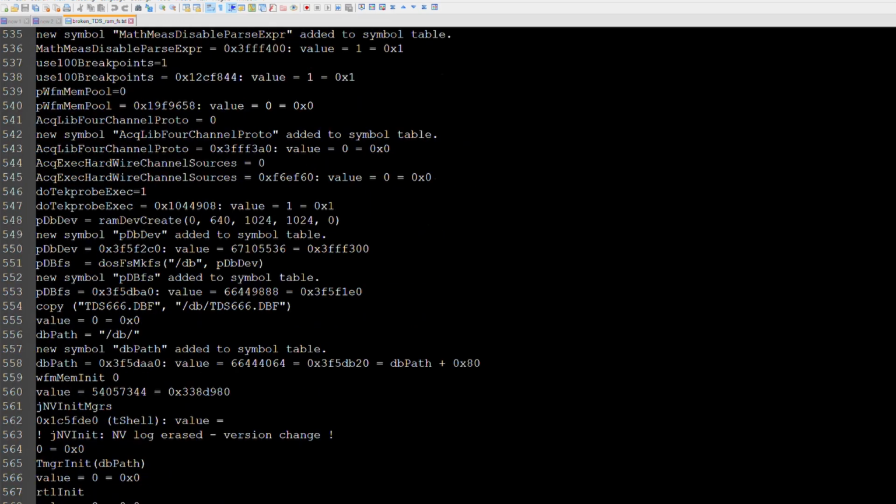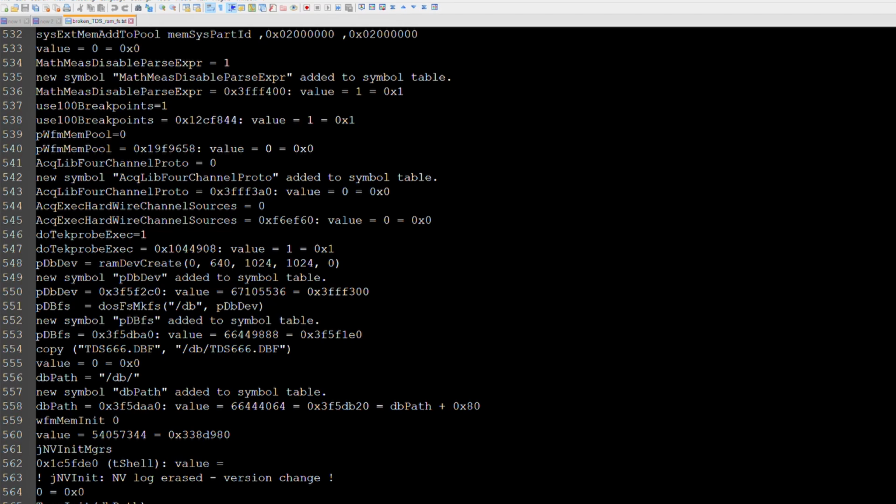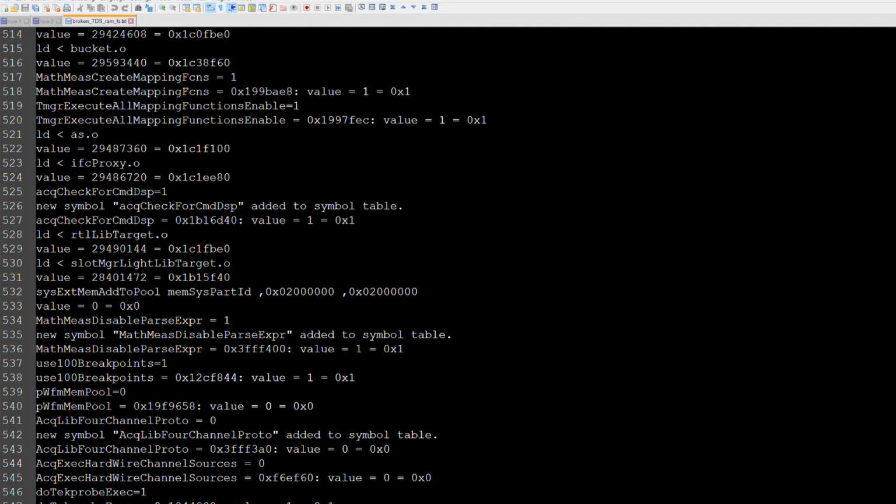We will reprogram the acquisition board FPGAs as well, because due to heat and everything else, they sometimes forget their settings or lose the configuration, and sometimes you have just one bit flip, which may cause acquisition errors. That's another matter. We'll do some cleaning and everything else, and then we will be done with this scope.